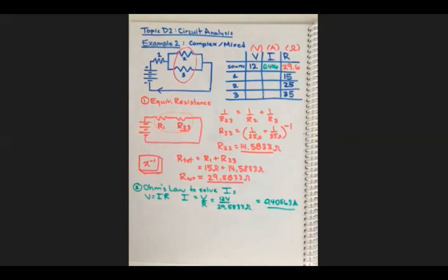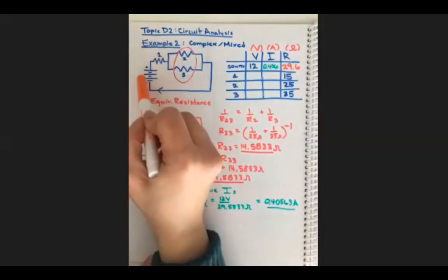And then what other options do we have here? It doesn't look like we can move forward with Ohm's law for any row, but now we have to start somehow using KVL or KCL. So let's start with, KVL, we can't move forward with it because of the same reasons at the beginning we couldn't start with it. KCL is, does this current lead to some other location without being split? And it does, right here.